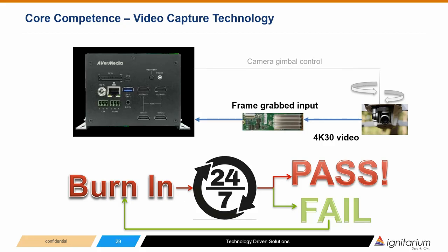How do we do it? First, we integrate drivers of frame grabbers with Jetson BSP. Then, we take extensive length of time on stress test where burn-in is conducted 24 hours a day, 7 days a week. Once a test fails, the engineer team is engaged to take necessary approaches on justification. Then we run the 24/7 tests to be sure that this procedure passes quality assurance before the product is launched. This will come back and forth a few times due to the complication over sorting compatibility among camera, frame grabber, and the Jetson itself.